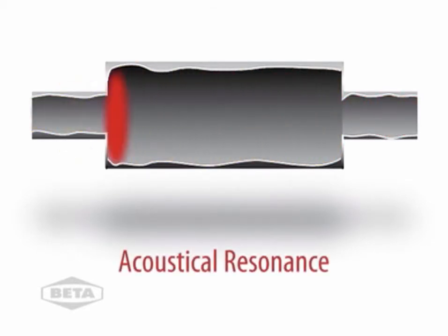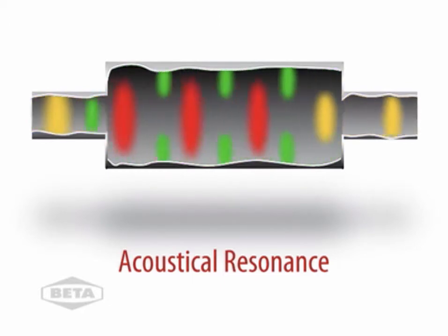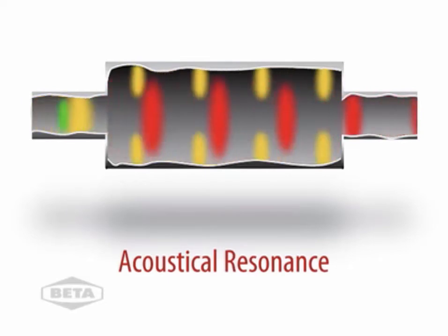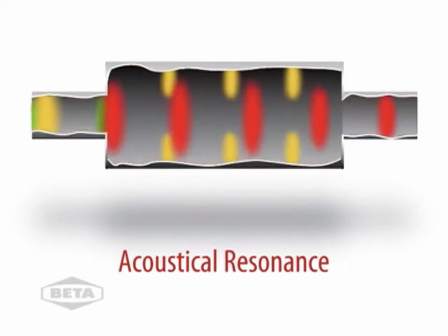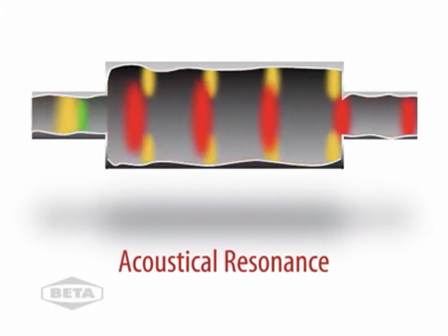This is called acoustical resonance, because the reflections are in phase with the primary pulse. The pressure wave can be amplified significantly, even up to 50 times higher than the original wave. If this acoustical resonance happens, then violent shaking and pipe failure are likely to occur.